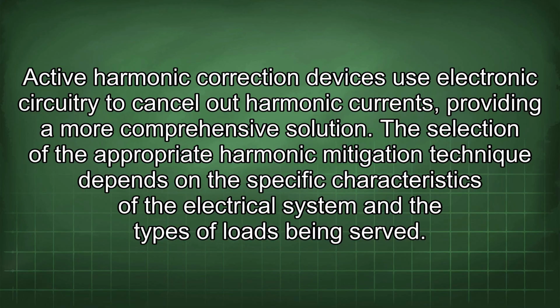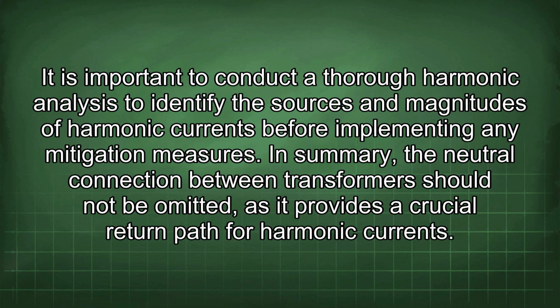The selection of the appropriate harmonic mitigation technique depends on the specific characteristics of the electrical system and the types of loads being served. It is important to conduct a thorough harmonic analysis to identify the sources and magnitudes of harmonic currents before implementing any mitigation measures.